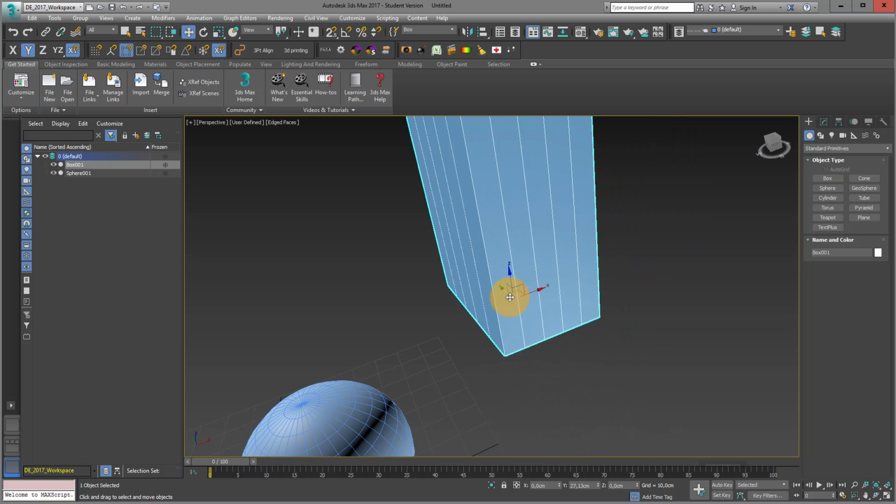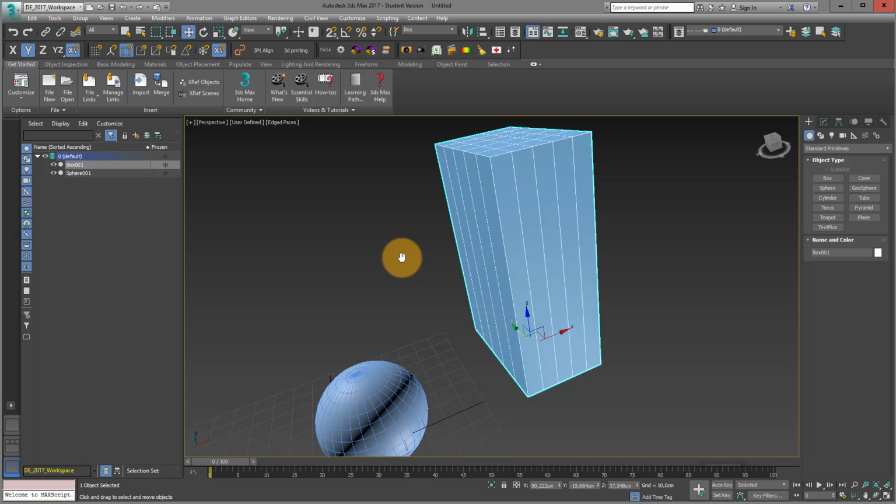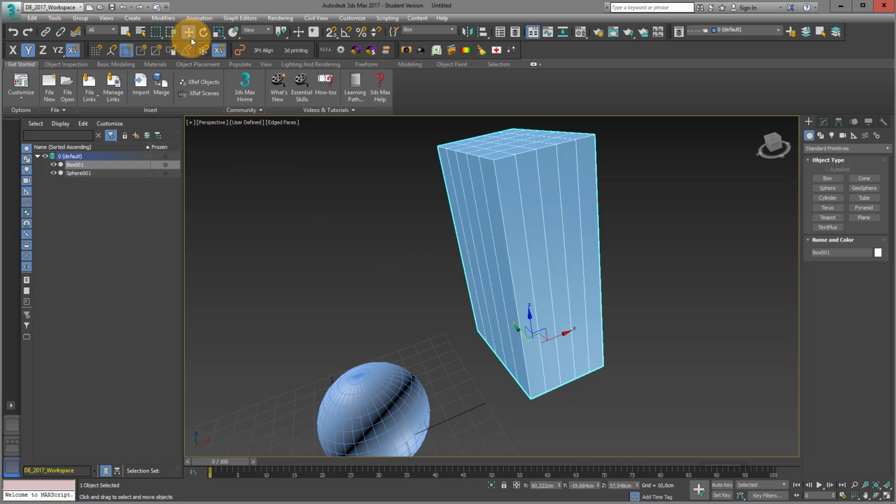Normally, this should be on, and when you move it, you can just see that also this has an impact of your setting. Okay, so far we only moved objects in the viewport in look and feel, but not with proper measurements and proper numbers. So what you can do is, if you go on right mouse click on move, then you can just move objects with precise values.